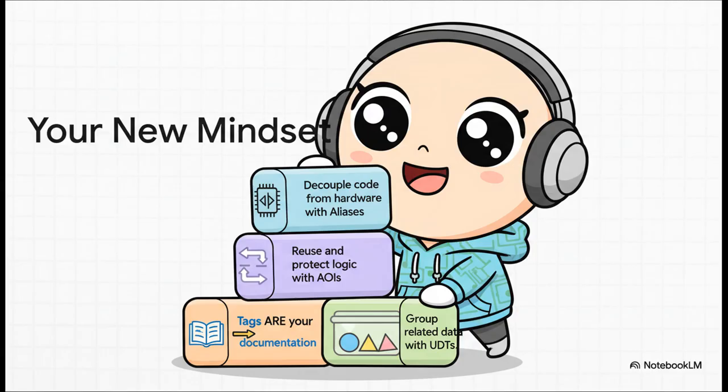So, to really get the most out of Studio 5000, you have to start thinking this way. You have to internalize these key ideas. Your tags are your documentation now. You should always be grouping related data with UDTs. You need to reuse and protect your logic with AOIs. And you have to decouple your code from the physical hardware using aliases. This is the new way.